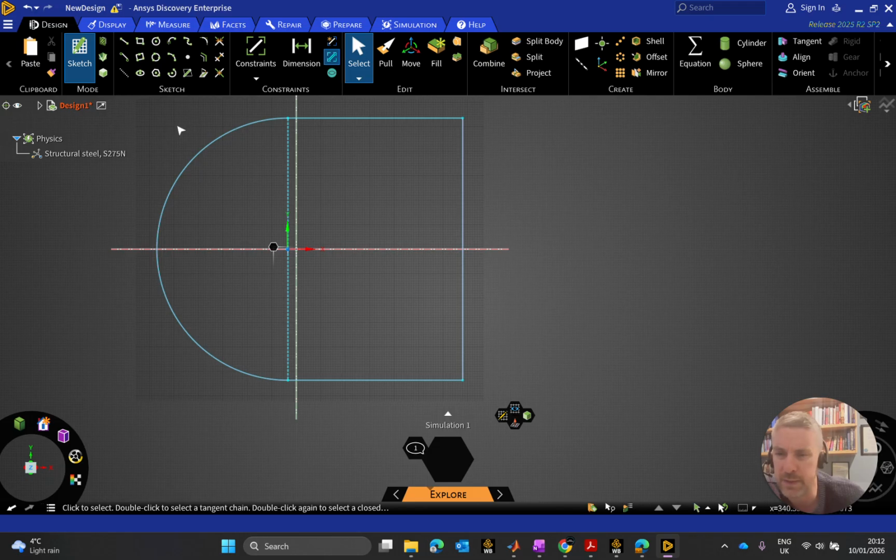But what I'm doing is including a lot of area here in which I'll have to mesh or use up cells or elements, in areas of very little interest or very little change with respect to what this airfoil does on the flow field. So by bringing this round into a radial curve like this, I'm excluding these areas down here, which are going to have very little impact on the aerodynamics of anything immediately before, above, below, or indeed aft of the airfoil itself.